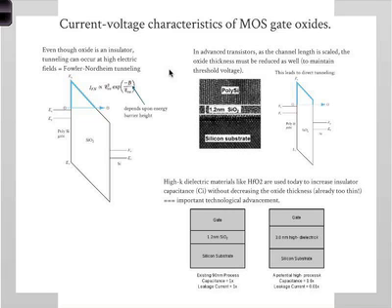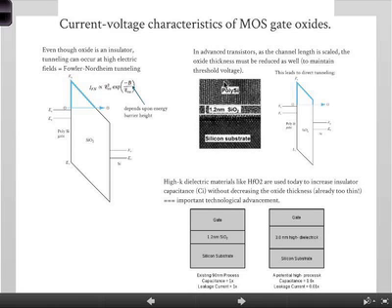They're very, very small. And it turns out, when you scale things in this direction, we'll talk about this more in chapter 9, you need to scale things in this direction as well. Otherwise, you end up with big fringing fields and so on. So you have problems in your current characteristics, which means that the oxide thickness has to be extremely thin. So an example is shown here.